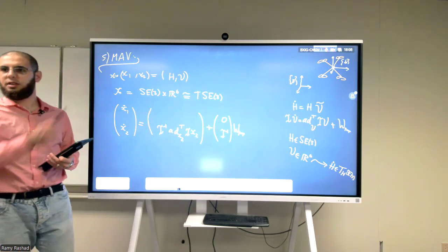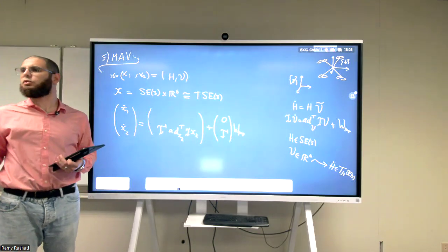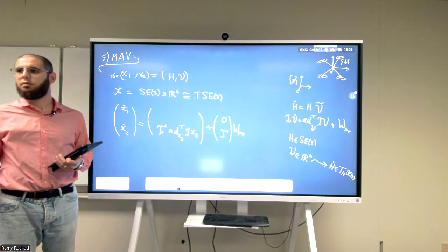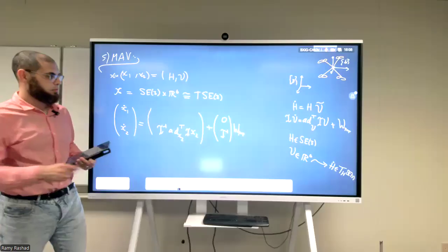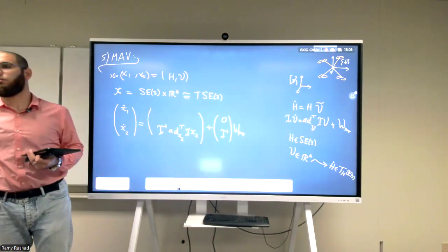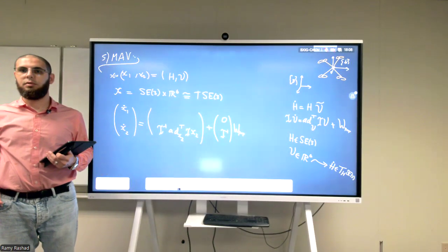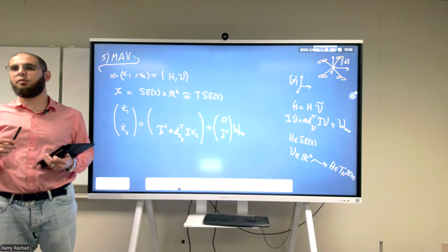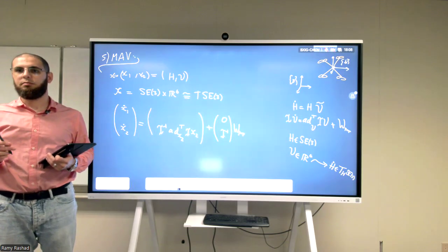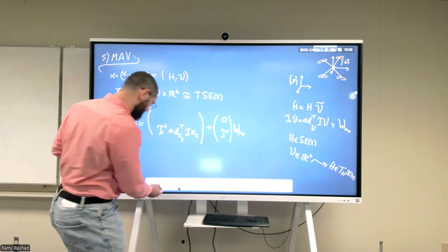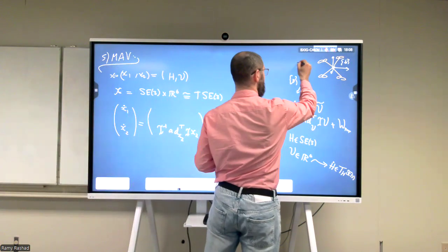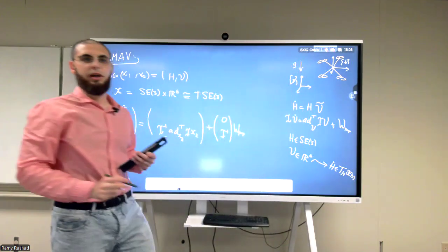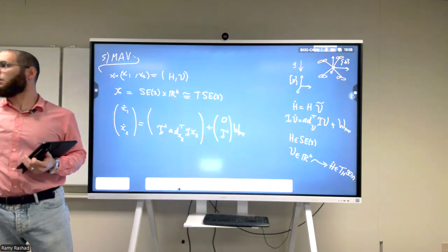That's weird, right? Because the previous ones, they were function of x1 also. The wrench due to the propellers only. Here, the input is the input. There's something missing in that rigid body equation. What is it? Gravity. What is the gravity term? You don't see it, right?